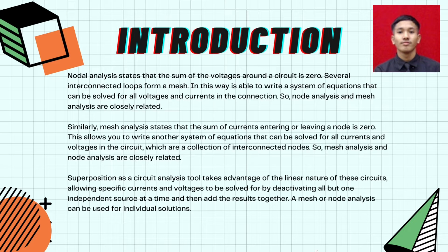Superposition theorem as a circuit analysis tool takes advantage of the linear nature of the circuits, allowing specific currents and voltages to be solved for by deactivating all but one independent source at a time, and then adding the results together. A mesh or node analysis can be used for individual solutions.